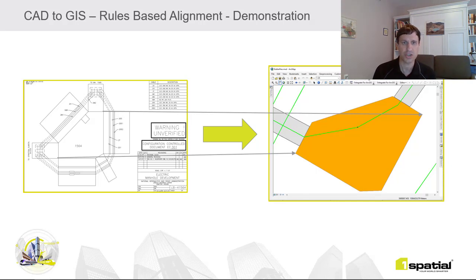NASA challenged us to show how we can automate the process of taking a set of electrical manhole DWG drawings, identify all the objects, including the feeder information, identifying the spatial location of each drawing, then shift, scale, and rotate the drawing to fit into the GIS. Then identify each feeder line, the number of times it wraps around the manhole, and where each feeder line is coming and going. The result will be understanding how the feeder lines are distributed through the network, and then being able to leverage Esri's utility network tools to trace the network.